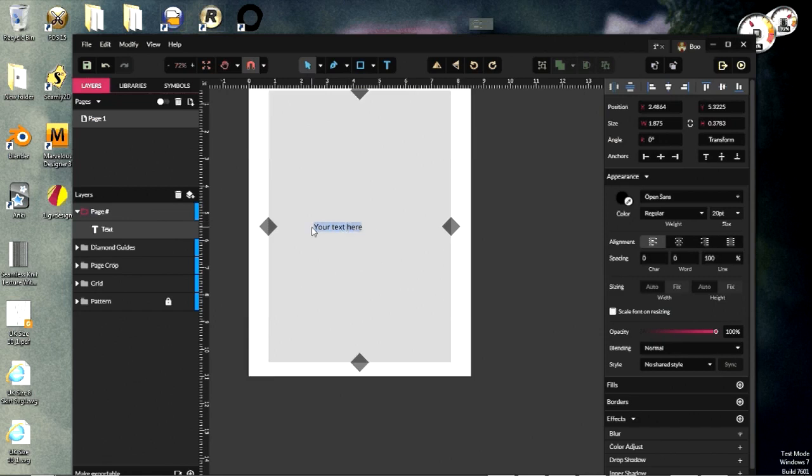The standard format for tiling your print and creating rows is you put the letter name A to the first row, the next row is B, next row C, next row D, and then of course 1 for the first page of that row. So the second page of the first row is A2, the third page of the third row is C3, and so forth. So I'm going to put A1 for the first page,